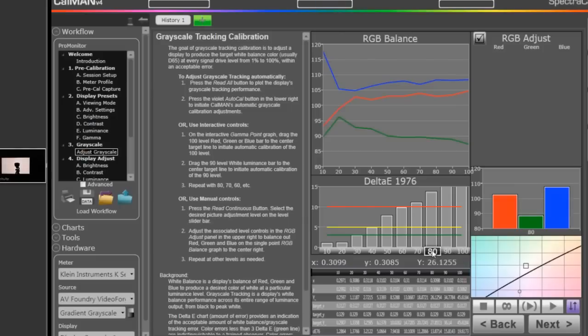That changes the test pattern level on the display, as you can see on the webcam. I'm going to start taking continuous measurements. And now I'm going to go access the white balance controls in the display for the high brightness settings for white balance. So opening up the picture menu, I'm going to go into the expert control menu and scroll down on that.